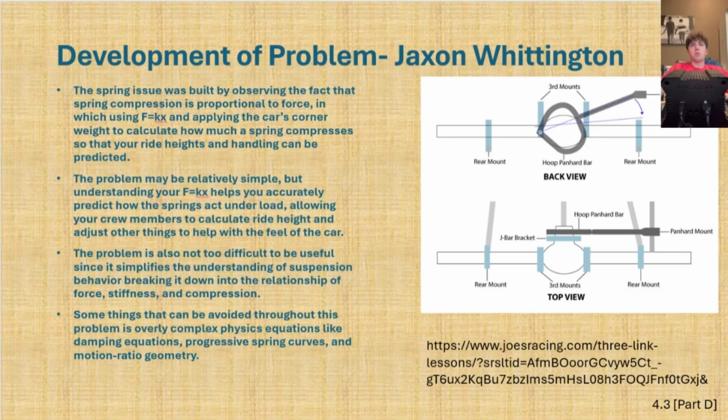So this problem, the whole entire spring problem, was developed on the fact that spring compression is 100% proportional to force. Using F equals kx, and the car's corner weight, it's possible to predict your maximum ride height, your suspension movements, things like that, whether it's just your rear end, your shocks, your springs, all kinds of different things play into this.